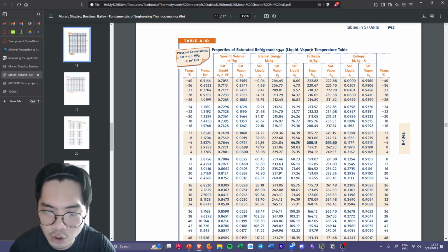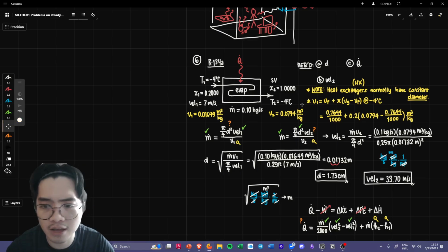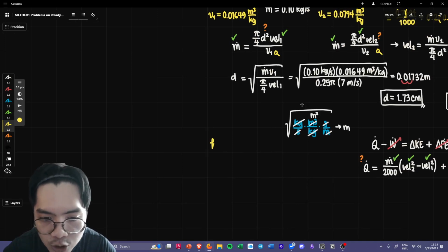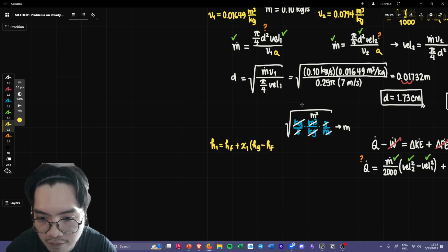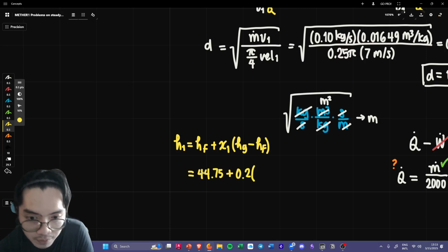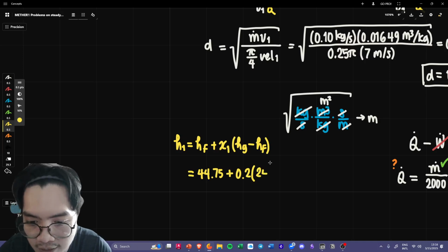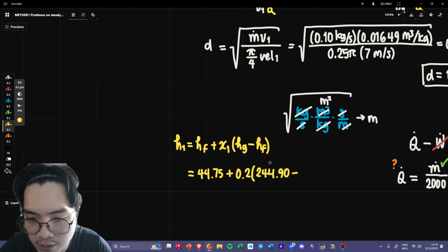So now we will go 44.75 and 244.9. You know what? I'll just put it here. Your H1 is going to be Hf plus X1 times Hg minus Hf, which will now be equal to, what is Hf again? 44.75 plus 0.2, it's 20% dry, times Hg minus Hf, your Hg is 244.90 minus Hf, that's 44.75.